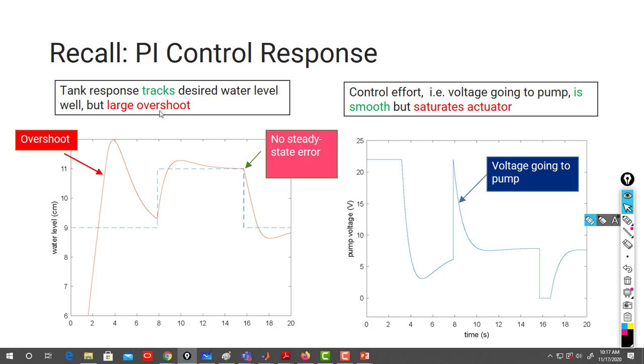If you remember, compared to the derivative term, it dampens the overshoot. But this, it will amplify the overshoot. It may lead to instability in the end, if you wish, the integral term. But it has the advantage of eliminating the steady state error.